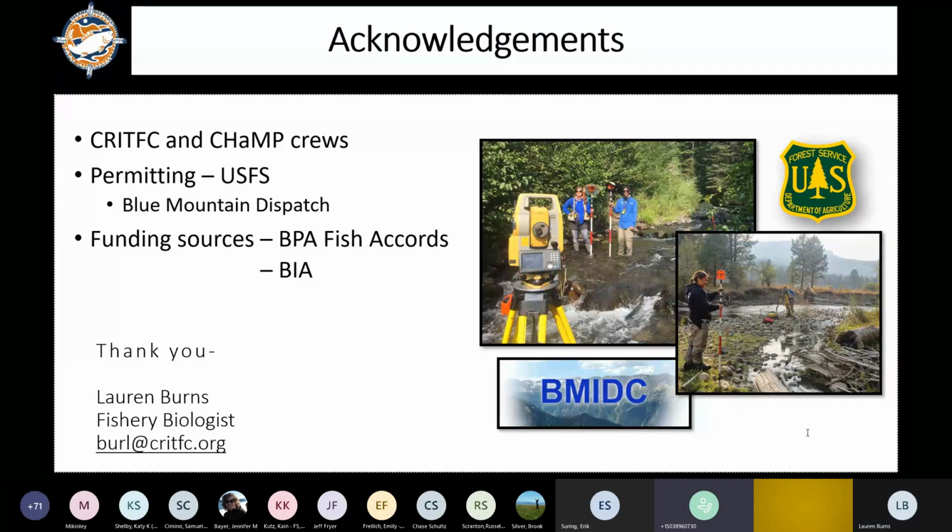Okay, great. Another question from the chat says, does Litchi work well for grid mission flight planning? So Litchi requires a little bit more time investment into planning your flights on the front end. You're able to set different camera angles at a given waypoint. It's like building a PowerPoint presentation. You're building an animation. So one animation would be like, take an image nadir, so looking directly down. Then at that same point, adjust the camera angle to offset at 20 degrees, and then take another camera angle. But once you have that developed, you're able to use that as the basis for future flight plans.